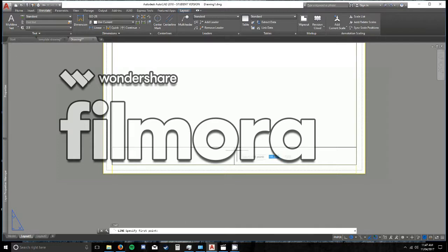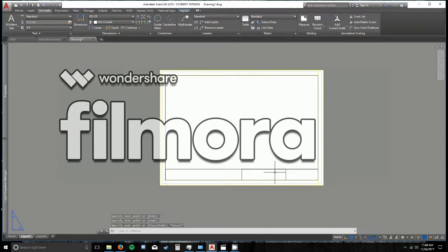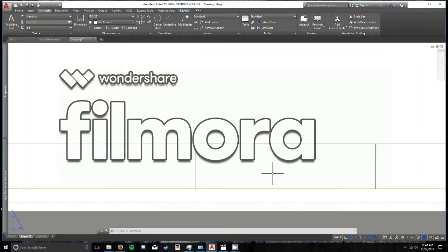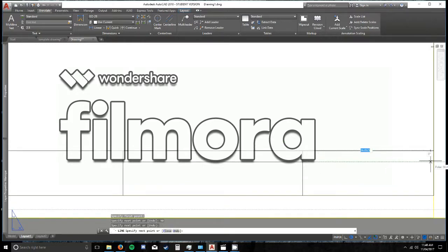And then for the last bit, go here, measure 80 mils across at 0, and down again. And now you've subdivided your area into a text box here and then more useful information here. So to create the text box, we get here, measure down 5 mils is normally a good start. And then drag it across, and then if you want, keep going to the next one.